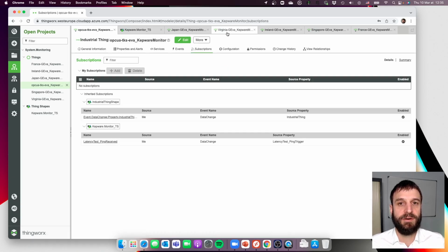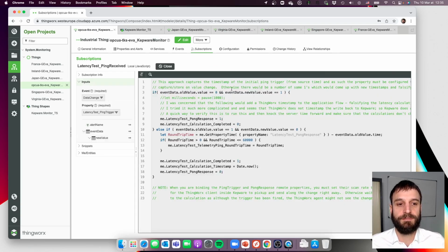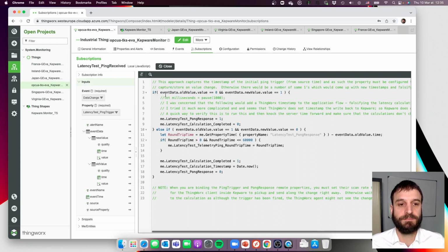And from there, I'm firing off a subscription. Ping received. And this subscription is just looking at which transition did I just make. 0 to 1 transition being the becoming true. I'm going to essentially take a value. I'm going to set the Pong response into this other tag. So I'm using a secondary tag to send a value back down. And I'm going to reset the calculation completed Boolean.